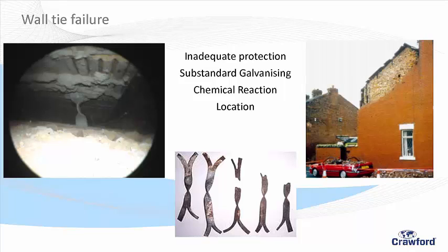Why have they got something going on there? Thermal expansion? No. So if this was the outer wall, and water wanted to travel in down this, what's going to stop it from getting all the way to the wall? A drip. So this creates a little drip, and the water goes down to the cavity and back out again. But the water gets through. If the galvanizing is not great, it's going to corrode. And here is an example of an outer wall, unfortunately landing on a neighbour's car.